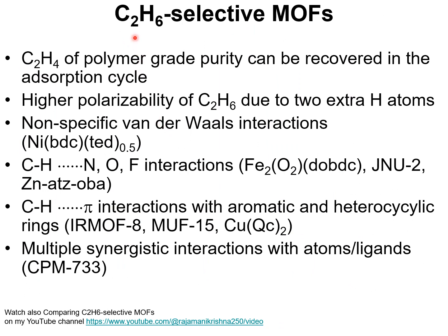There is currently a great deal of research focused on the development of MOFs that are selective to the saturated alkane. The advantages of C2H4 selective MOFs is that ethylene of polymer grade purity, typically 99.95% plus, can be recovered in the adsorption cycle.